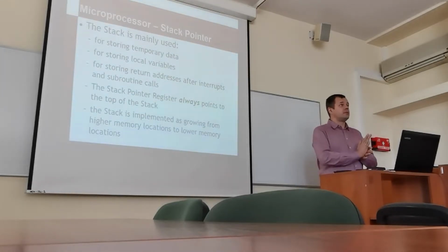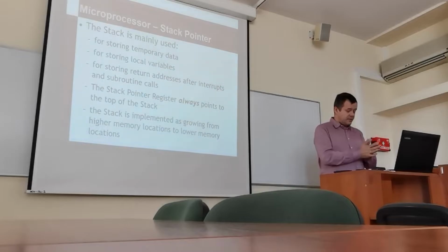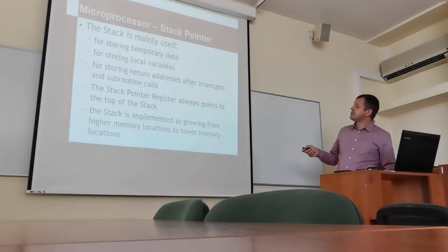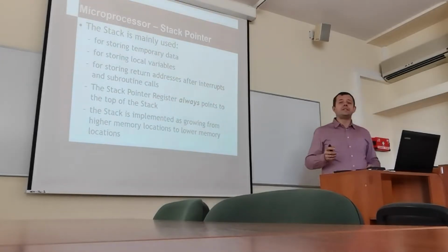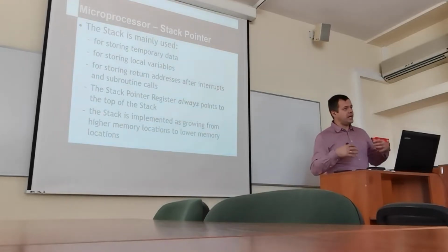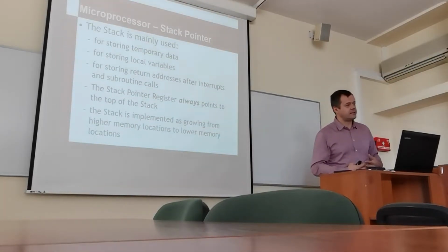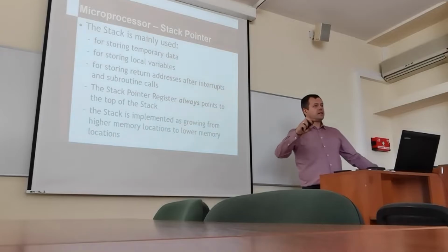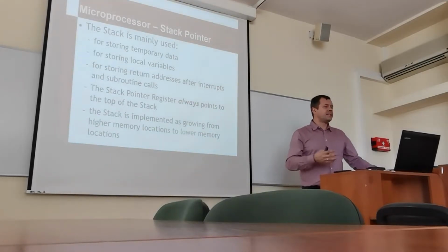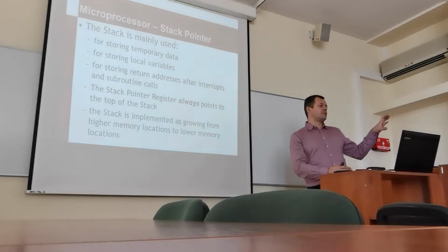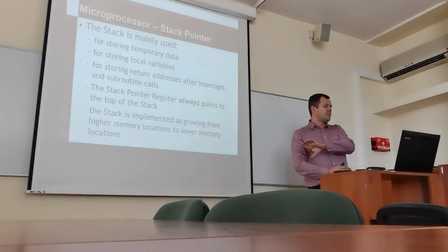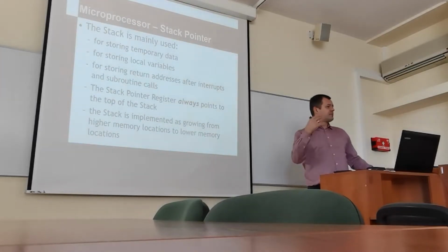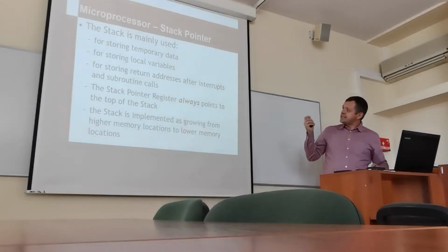but also this stack plays a very crucial role in storing return addresses in various subroutine calls. Without stack, we are not able to make any nesting, any procedures nesting in the microcontroller. So we would not be able to write maybe not recurrent software, but even simple software where we call functions, so that we call a function and then the function calls another function. Because the stack is used to remember the return address, where to return to. So that's what the stack is for.